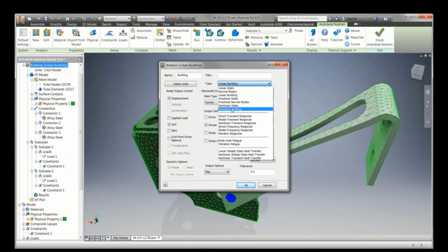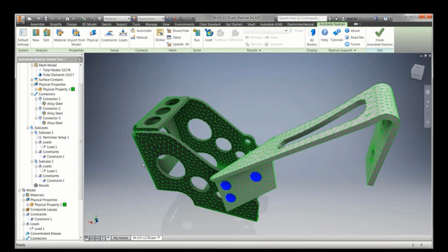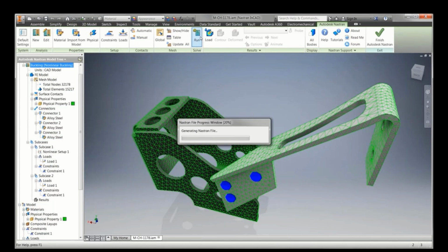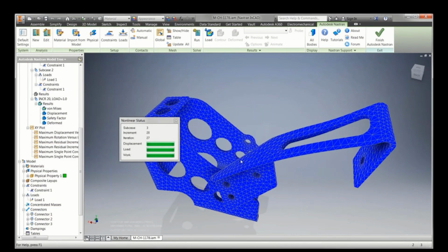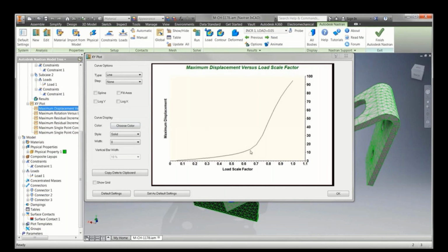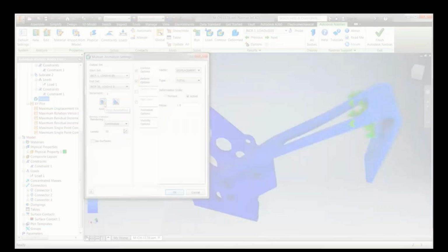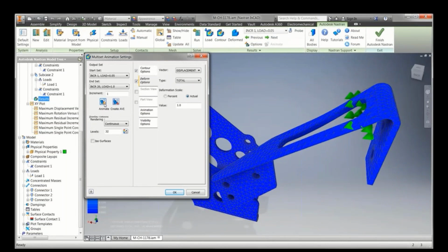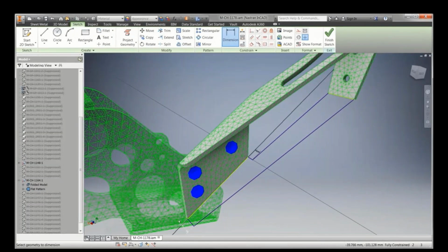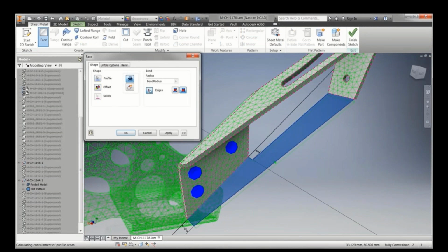Determining stress and deflection gives insight into design integrity, but does not tell the entire story. Is it possible that your design may buckle at some point as the load is applied? This can only be checked by running a linear or nonlinear buckling study type. They have the power to provide you with the maximum load your design can handle before it loses its stiffness or undergoes catastrophic failure.